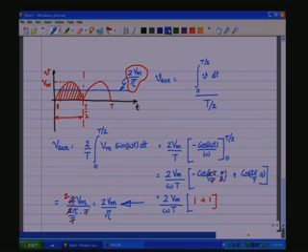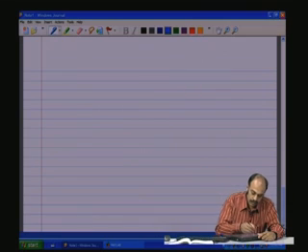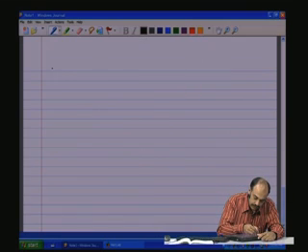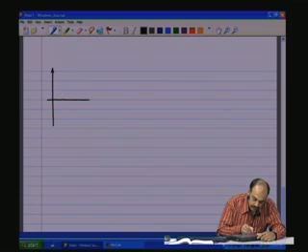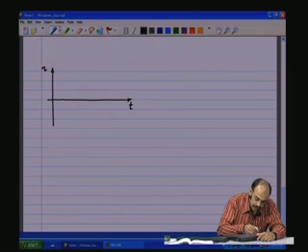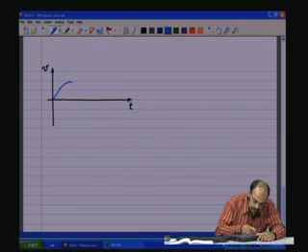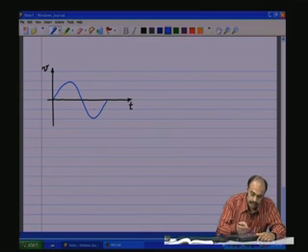Now, a slight modification to the circuit is a clamper, that is from the absolute value circuit you could use a clamper where the voltage of the sine wave is not passed through an absolute value circuit, but it goes through a clamping circuit such that as long as it is positive the input and the output follow.